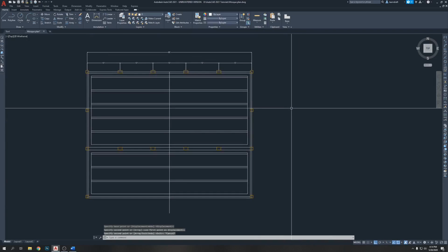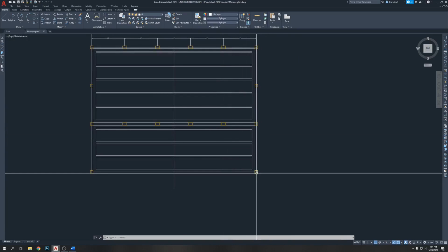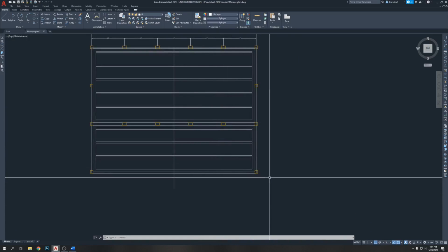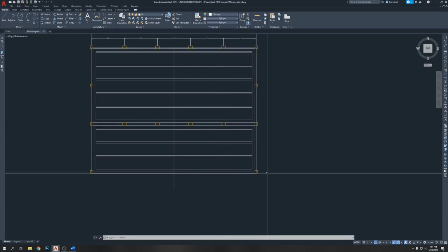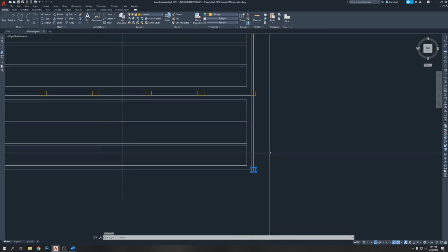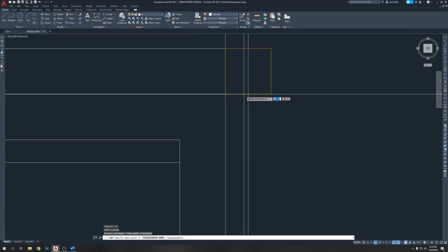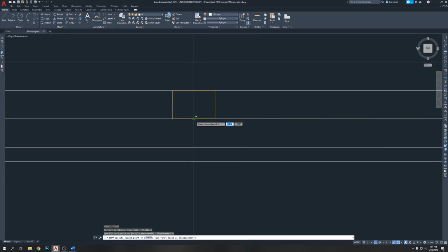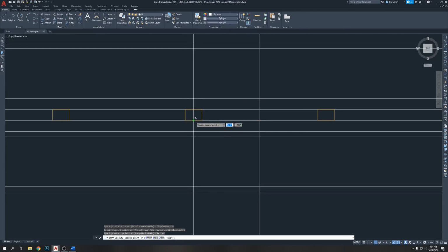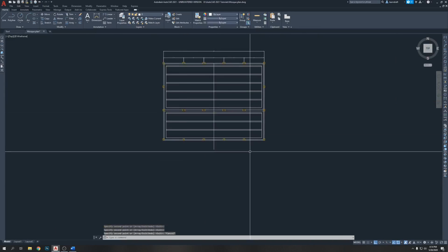So these columns are good now, and we're gonna put this 12-inch column to align with this, because we do not need a very heavy column there. How are we gonna do that? The center line is aligning with the center line, so I'm gonna click this one, copy, pick from this center and place on this center. So our beam is going to be aligned with the columns.